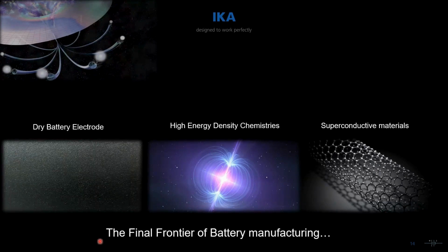We have a much higher energy density and a faster charge time. That comes from not having to evaporate your solvent off and leave any interstitials or void spaces in your electrode. You're instead making use of the entire volume as electrode material.